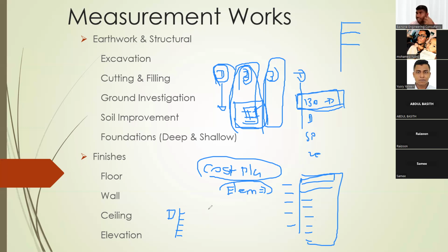They will do an estimation. The contractor's tender department will collect the documents. The estimator will have a QS under him, so they will give it to the QS to check the quantities mentioned in the BOQ. The estimator will coordinate with the suppliers and subcontractors to arrange the price, and the QS's quantity and the estimator's price are put together, and they submit the tender.